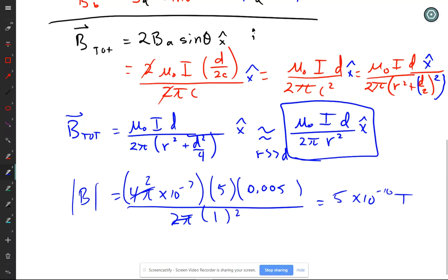The reason the wires have the two incoming and outgoing currents close together is so that it comes to very small amounts like this. If you had just positive current going in this direction and nothing coming back beside it, you'd have much bigger magnetic fields, much more interference.